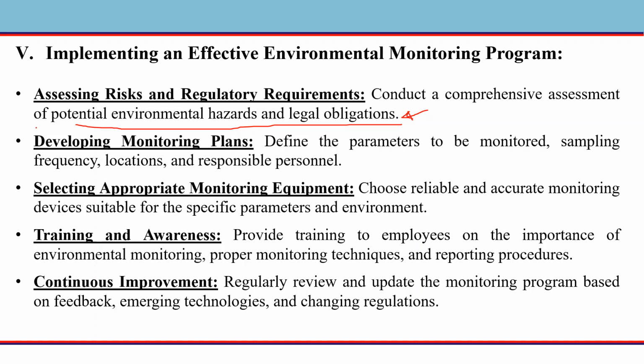Then based on this information, we need to develop monitoring plans. Okay, so we need to define the parameters to be monitored, then sampling frequency, then the locations where we need to sample, okay, or we can get the sample, and responsible personnel. Okay, so who will be responsible for all of these things? So this is related to developing monitoring plans.